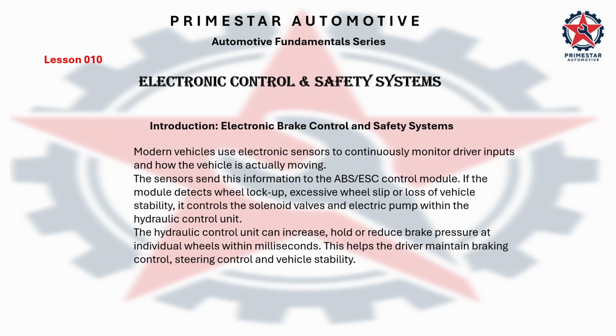If the module detects wheel lock-up, excessive wheel slip, or loss of vehicle stability, it controls the solenoid valves and electric pump within the hydraulic control unit. The hydraulic control unit can increase, hold, or reduce brake pressure at individual wheels within milliseconds. This helps the driver maintain braking control, steering control, and vehicle stability.